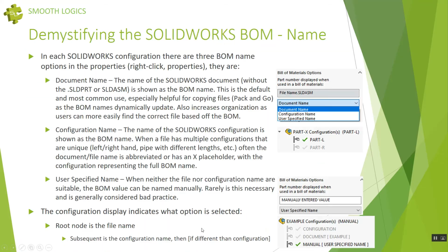So, bills of material. Bills of material. One of my favorite subjects ever. So the bill of material is a way in SOLIDWORKS to automatically generate basically a list of stuff that's in a given assembly for outside consumption.